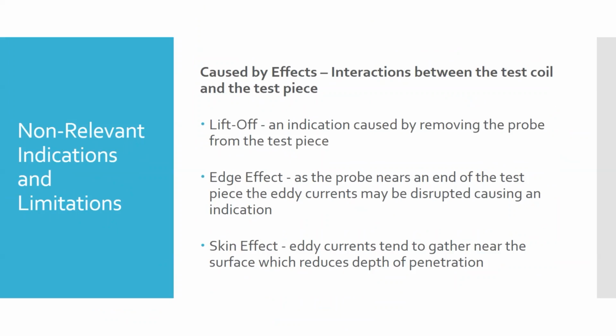So back to our origin point, we'll see that indication. If we had crack indications, here would be our small, medium, right? We've tested different cracks, different known cracks. But you can see an edge effect would start to look like a very large crack, but it would keep going and going. And then we would reach the point where that probe essentially slid off the side of the part. And when that happens, it's going to shoot off the side of the screen and kind of work like a liftoff indication.